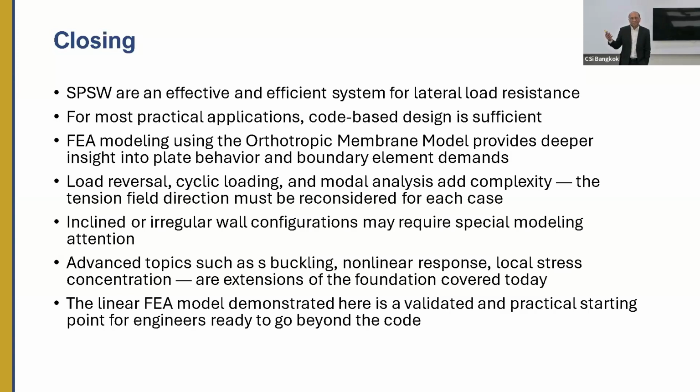In that case, it might be useful to use a finite element model, especially in most of the walls. You have coupling beams connecting. You have openings for the elevator doors. So the wall is not completely a panel. There are sub-panels there with the openings. In that condition, finite element analysis will be more useful. Advanced topics such as buckling, nonlinear response, local stresses, and local stress concentration can all be handled by extending the model using the nonlinear modeling that I showed you. So that's the overall summary of what we presented.